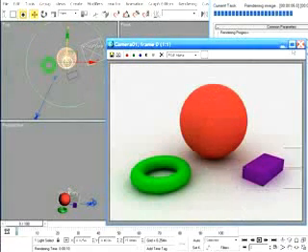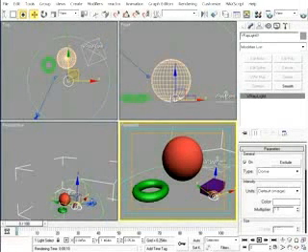So position means nothing. One additional note, you may or may not have noticed that when I first placed the light in my scene, I immediately changed the multiplier value. The default value of 30 is usually far too high for exterior scenes, so I changed it to 1 and got a more usable illumination.